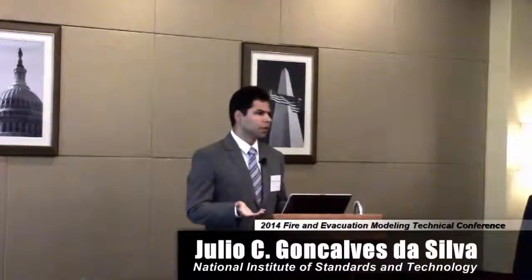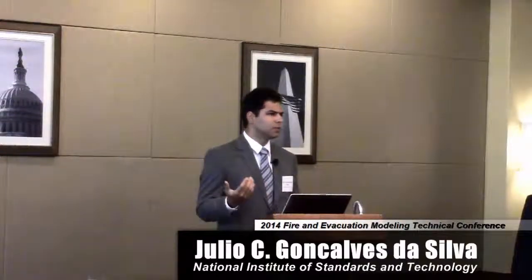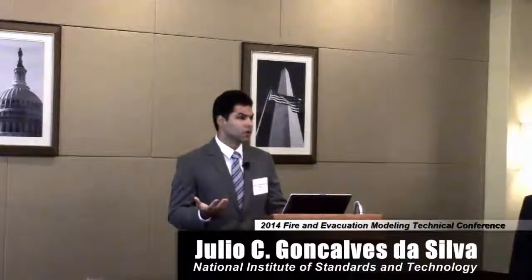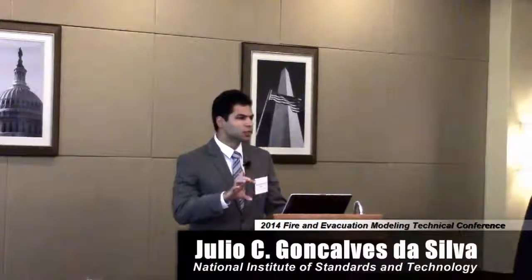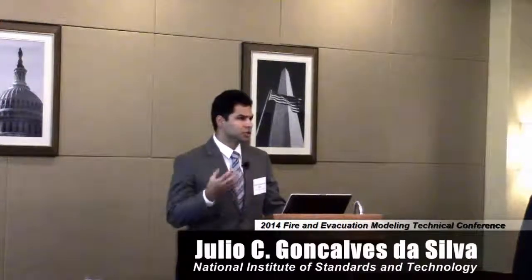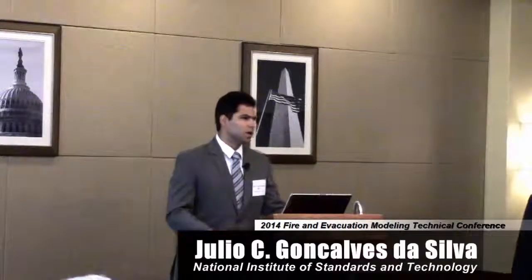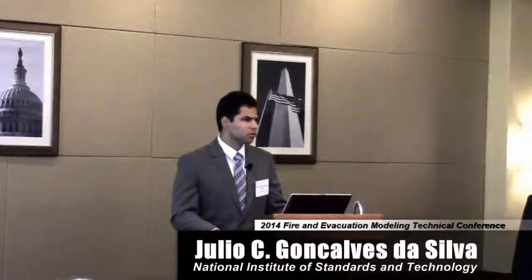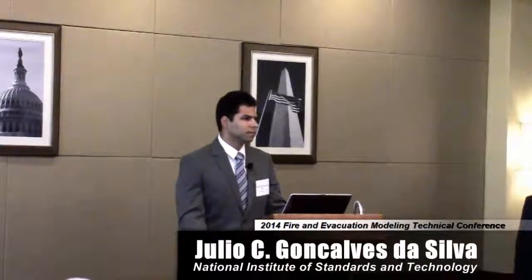Of course, if we change this number for a few, we will have impact, mainly if the radiative process is mandatory. For these localized fires, the heating of the structure will be handled by radiation because the fire is really close. So if you change this parameter, we will not have good results. We didn't try to do that, but that's what we expect.